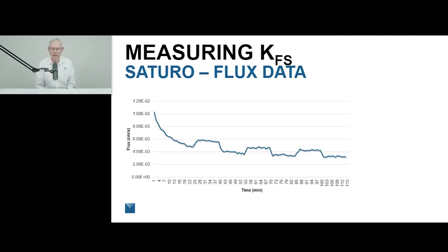This shows a typical run. You see a high infiltration rate at the beginning, as we expect because of the matrix forces drawing the water in. It finally levels off after about an hour and a half. The final readings are the ones used for the conductivity calculations.